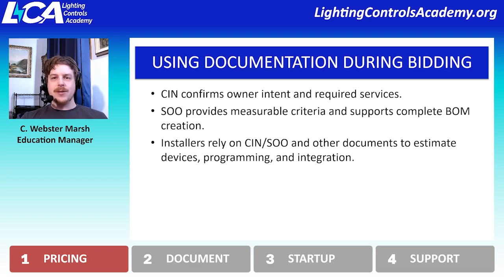And there are other documents and drawings or specs that they use to supplement. But oftentimes, if you have, for instance, a device quantity on your layout, if you show occupancy sensors and keypads in the documentation, the installers may just use that as their estimate. And if it's a schematic, as I've mentioned before, if that drawing is schematic only, that quantity is going to probably be incorrect.